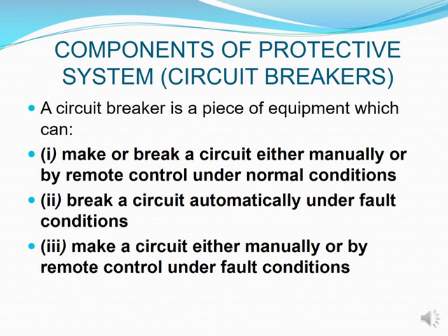And in what I've told you now, we usually connect our circuit breakers to your relays. But if you go to your houses where your distribution board is inside your house, then all of those switches that you see there, sometimes white, sometimes green, those are called circuit breakers, but they're of a smaller scale and they don't require the relay to be connected to it. They have that built into them so that the minute your house or your plugs or your lights go in an abnormal way, then it will quickly just trip. So that is under fault condition, it will break your circuit.